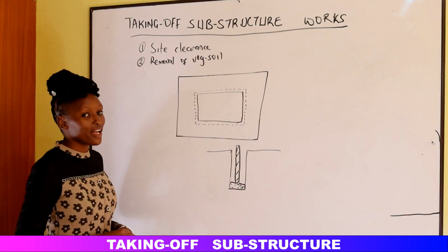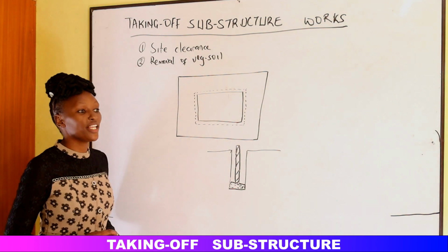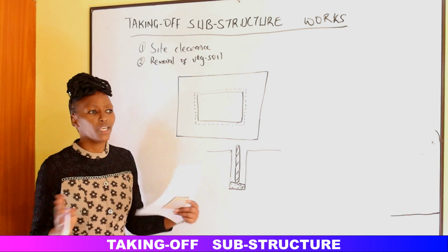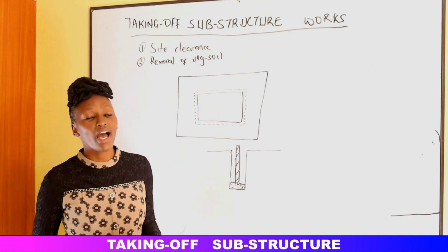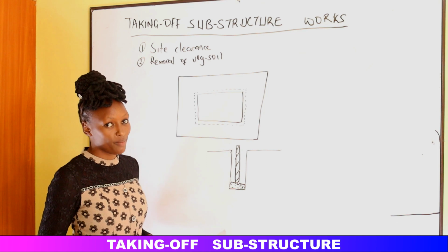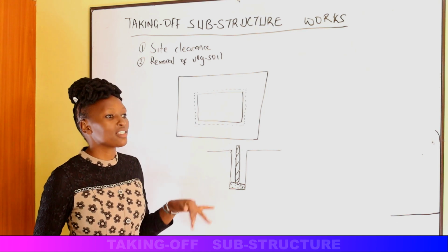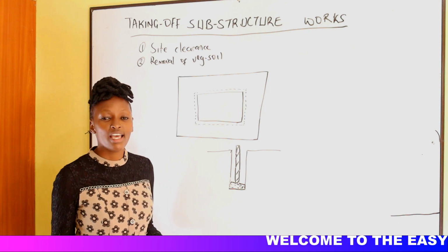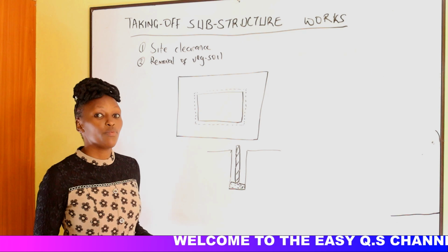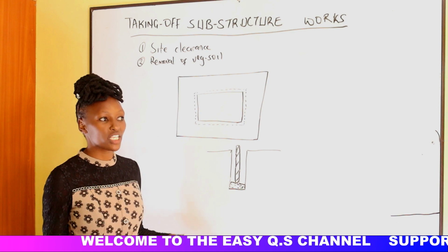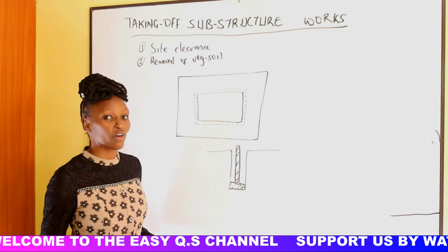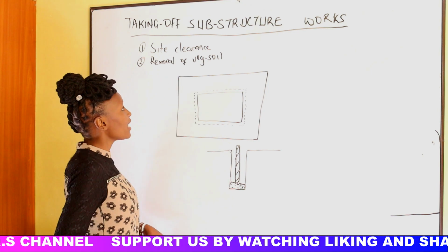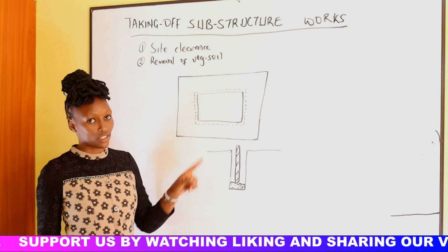All other works like demolishing buildings, actually maybe it's a big cost for demolishing a big building, that one will be accounted for in the preliminaries. What we measure in site clearance is the basic clearance: removal of grass, cutting down trees. If there are so many big trees, some extra cost is usually calculated in the preliminaries. Alright, so site clearance is usually measured in meters squared.